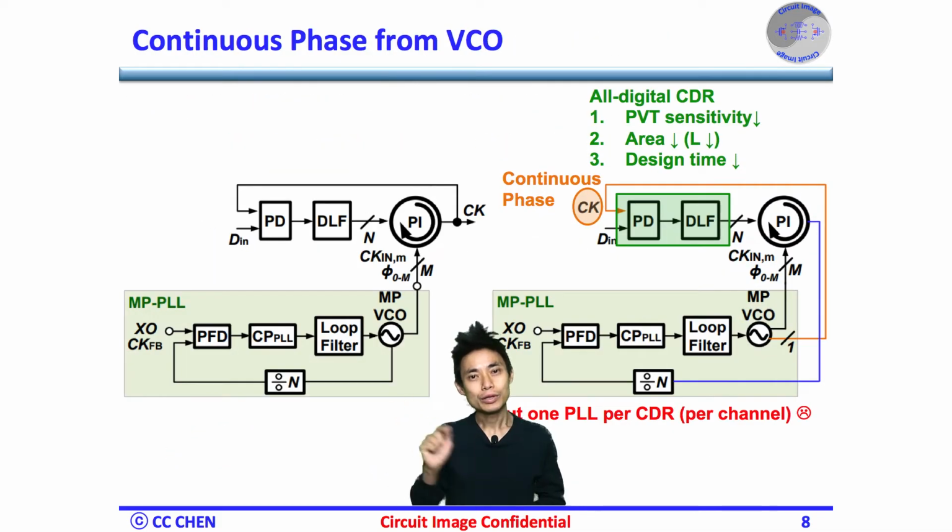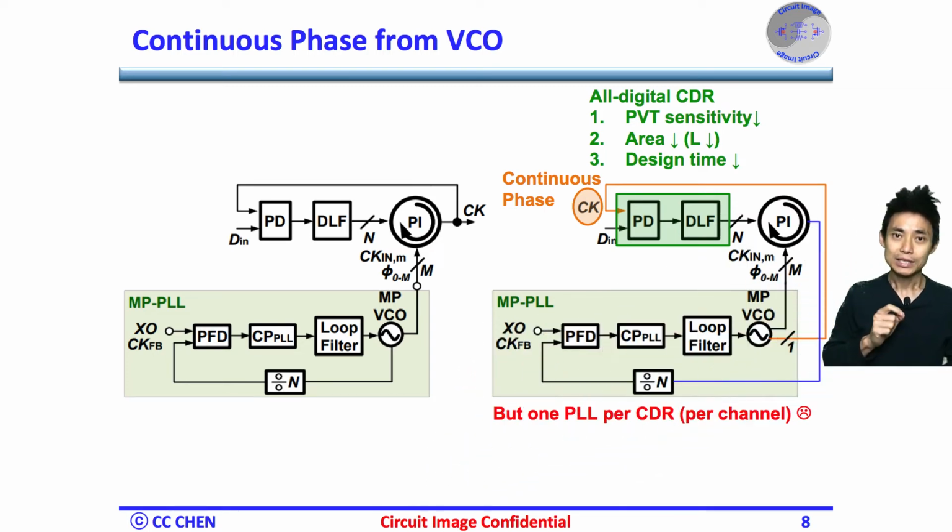Correct. To smooth out the discrete phase shift step is to swap the phase lag and VCO output connections. The discrete change in phase selection from the digital loop filter DLF in the CDR phase tracking loop can be smoothed out by the PLL loop's analog loop filter and charge pump. The PLL provides smooth frequency and phase drifting in the phase tracking loop. So, the revised PI-based CDR could still achieve the all-digital CDR benefits and have continuous phase adjustment.